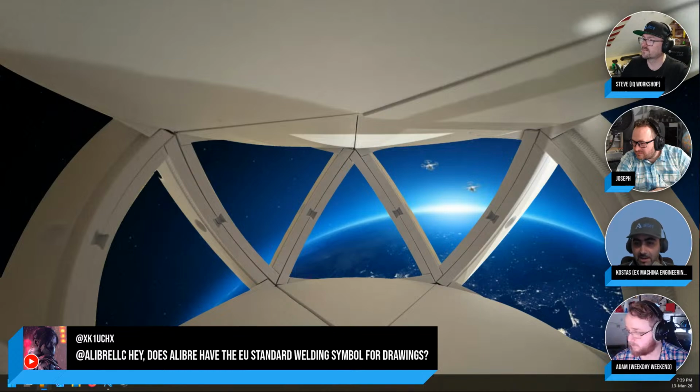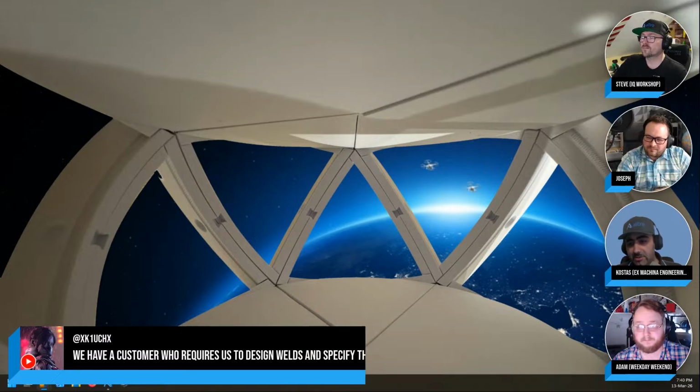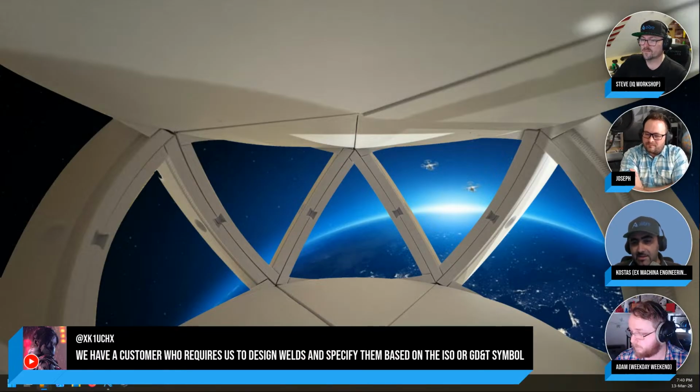Right? Bend radii and reliefs and all that. Most shops have a set of rules for that, right? For example, you're using a 2 millimeter thick sheet, then you'll be using a bending tool that has a 1.2 millimeter radius. And you need to know that, because they might even give you K factors, and if you design that differently, you might have small differences in dimensions in the final part.